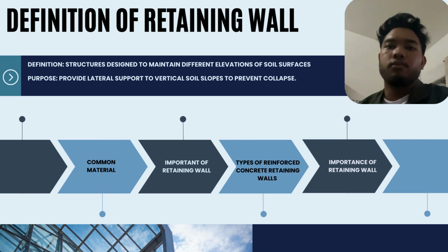Cantilever retaining walls are suitable for heights up to 6 meters, and use the cantilever action of the heel, toe and stem slab to resist lateral earth pressure. However, for heights above 6 meters, the design becomes uneconomical due to the increased earth pressure and moment. Counterfort retaining walls, which require more steel and a larger base, offer an alternative.